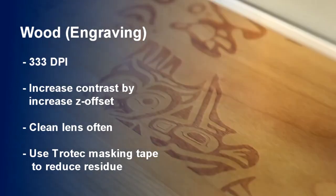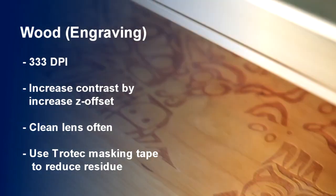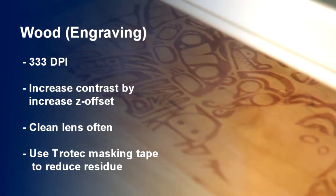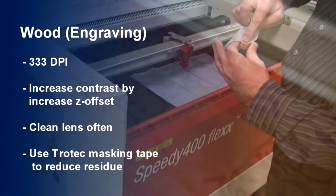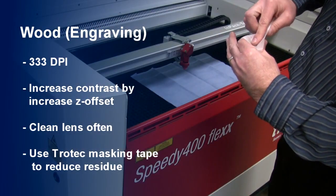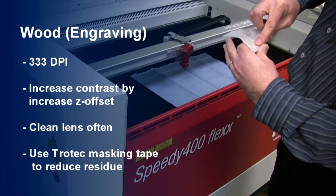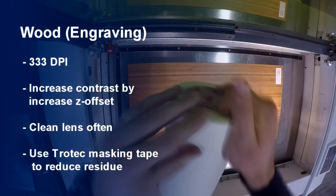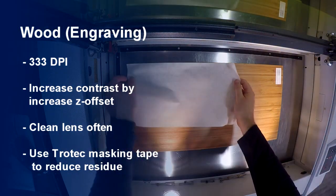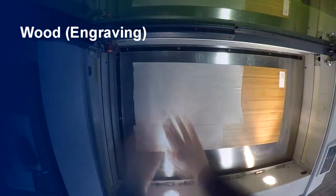Pointers for engraving on wood. For any engraving job, use 333 dpi. You can increase the engraving contrast by increasing the Z offset value. Engraving on wood produces a lot of dust, so if you're doing large jobs that require a lot of engraving, you may want to clean your lens or machine quite often. Use masking tape to reduce any of the smoke marks caused by the heat from the laser.